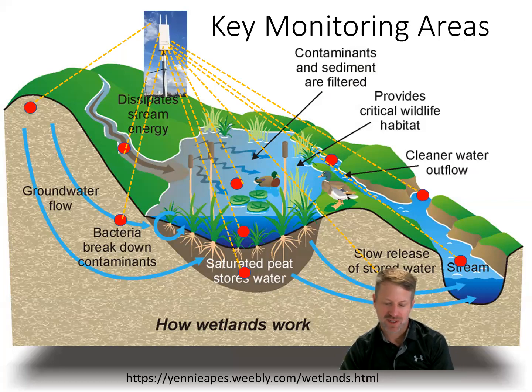To give an example, a gateway antenna that's 30 feet off of the ground will receive data from sensors that are located up to 5 miles away. So we can cover a pretty large area with one gateway. And these gateways are just a few $100s, or even less. If you have an indoor building, you can just plug one in. And there's one cell modem account with that gateway.